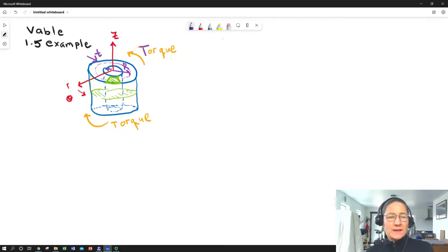I'm going to start out by getting an expression for the area of this section here, matching the color of my little section. I'm going to write it in terms of a radius in my radial direction and some differential angle in my theta direction. Of course I'm flat, so I don't have to worry about any thickness z. This is just an area, and it's going to be uniform in the z direction. So I can express a differential area anywhere that's going to include this slice of adhesive as r d theta, which is my ds, my circumferential distance, times dr.